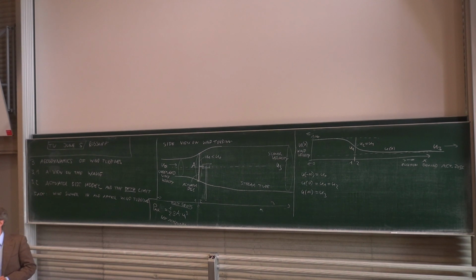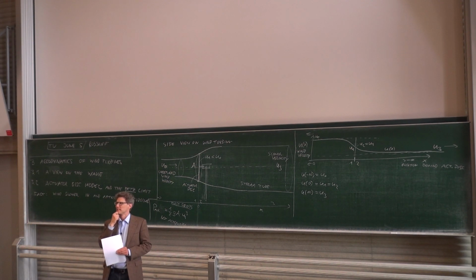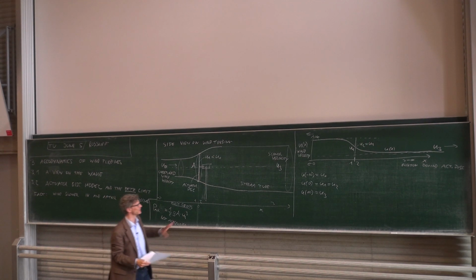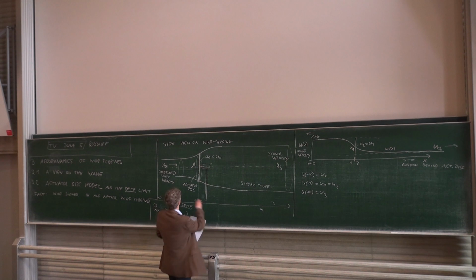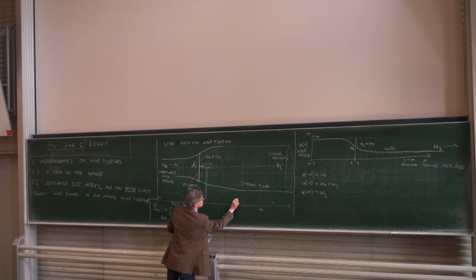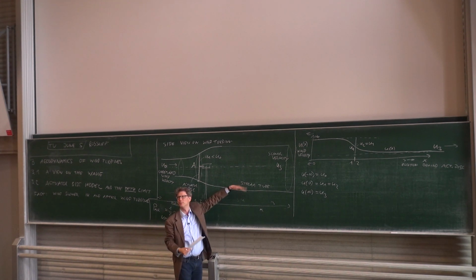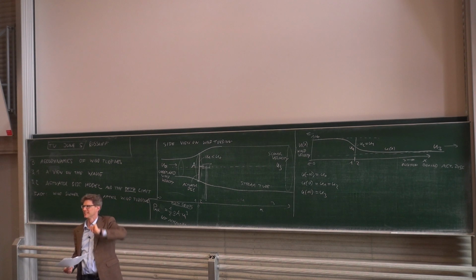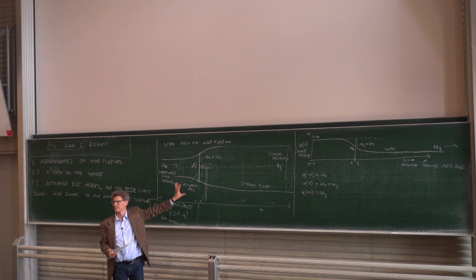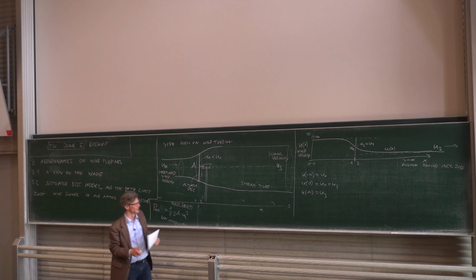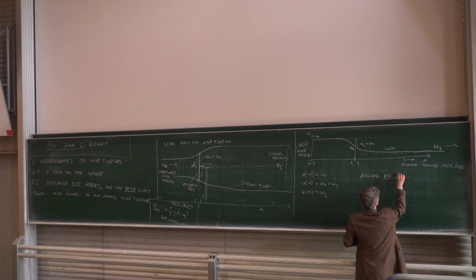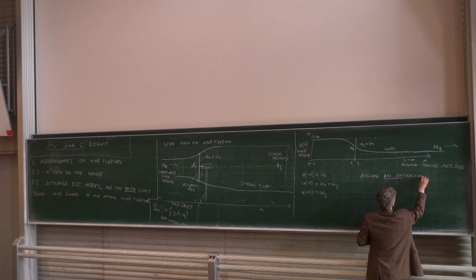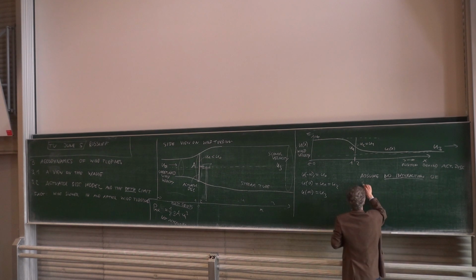After the actuation is kept infinity, wouldn't this become this? Yes, that was my answer to your previous question, but this is not what we cover here. The actuator disk assumes that there is no friction between the stream tube and the rest. So there is other velocity with u0 that flows always here, and they will not interact because there is no friction in the air. So that's an idealized model. In this case, we call it u infinity for this simplified model, not for reality. Maybe I should say this. Assume no interaction of the stream tube with the outside world.